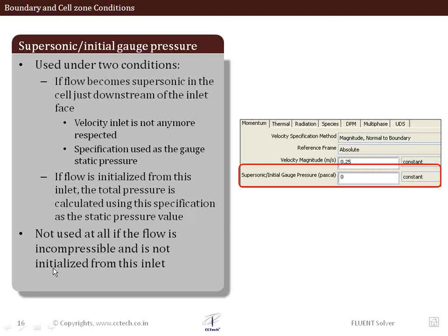Otherwise, if the flow is incompressible and you don't plan to initialize with this inlet pressure, then this value is actually not going to be used at all.